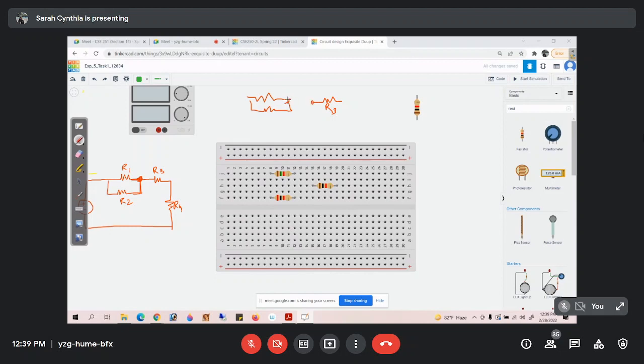So if we draw a wire from this particular node and connect it to terminal 1 of R3, we will be able to connect them. So that's what I did. I'm drawing a wire from this node in column 12 and dragging it towards column 15, which is terminal 1 of R3.